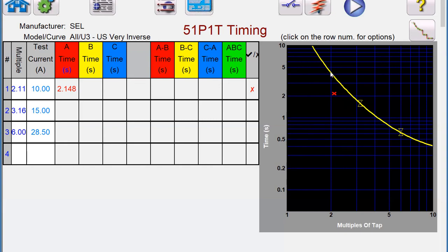If I hit run and select here, as Mohit came on and addressed, I have a communication issue going from my PC to my relay. I'm not able to perform the element masking. I would mask the 51P1T to OUT107 of the relay using the Accelerator software.